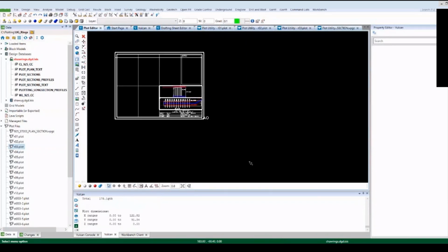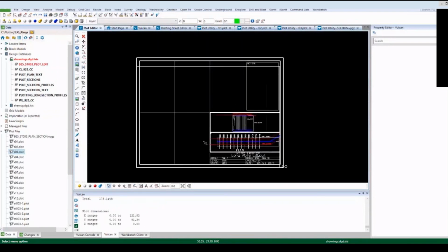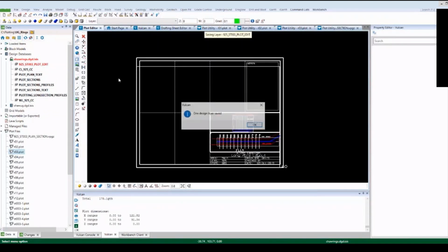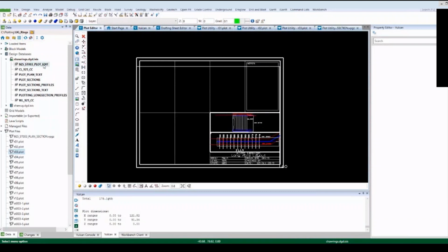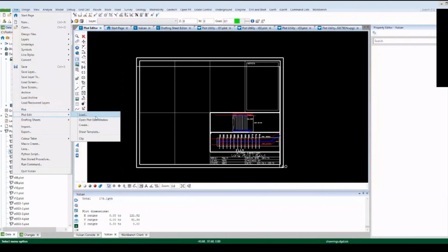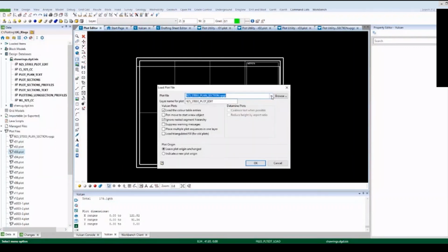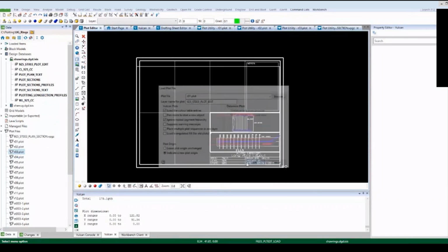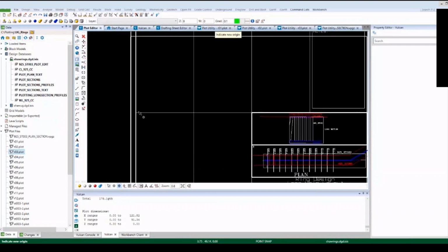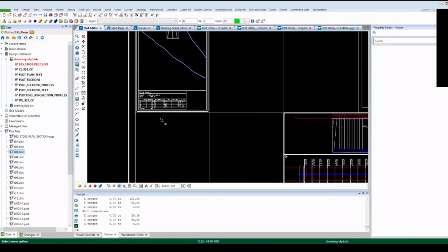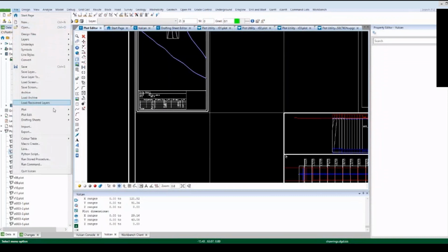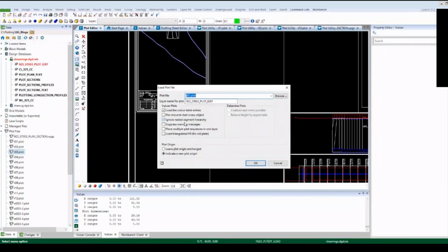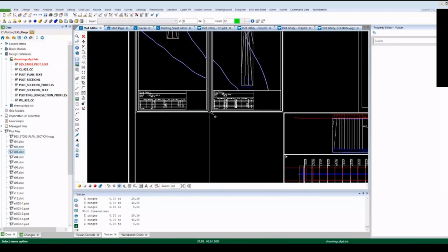In this one example, because I am going to pick my large arch E first, and I want the origin to stay the same. Now, as I go through and load in the individual, oh, there's my layer, it showed up in my DGD. In Plot Edit Load, now I'm going to go through, and on the same layer, I'm going to load up the individual ring sets and indicate a new plot origin for each one. So here we did ring set number 1, put that nicely in its place, and you just repeat the menus by going and picking ring set number 2 and fill in the rest of the space.